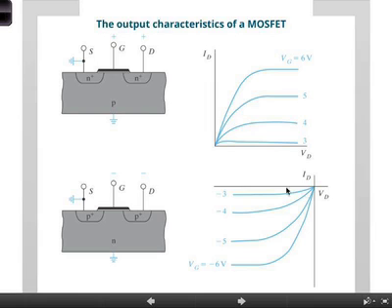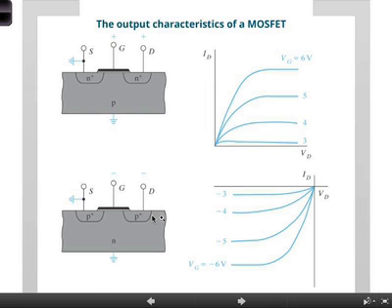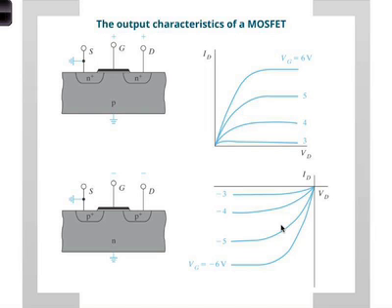With that convention, you can see, when the drain voltage is negative, the drain to source current is negative. Okay? Because the current is really flowing from source to drain. Okay? And then the IV curves make sense. So make sure you're fairly clear on what those mean. And of course, for the P channel, where will saturation happen? So I want you to think.